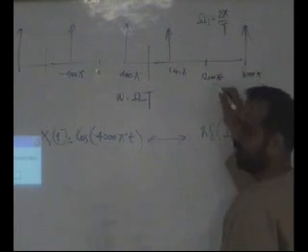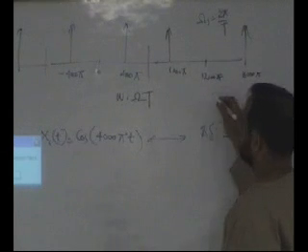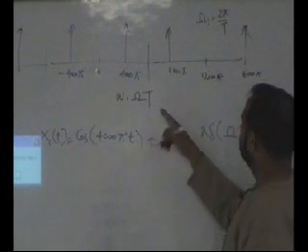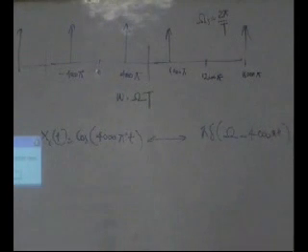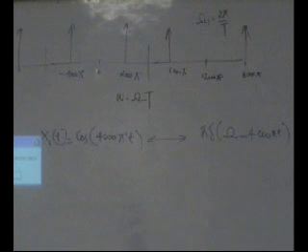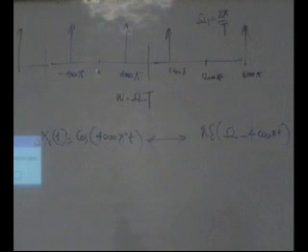The pi cancels out, giving 6,000, so T is 1 over 6,000. You divide by that, and you will exactly figure out that it will be 2 by 3 pi. Now, let's say instead of 12,000 pi I ask you to sample it at 6,000 pi, what will happen?